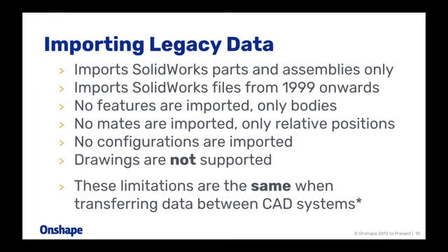a little bit more controlled and a little bit more the sort of thing you want to do if you're just making some slight modifications to a model. And again, what FeatureWorks does, it doesn't maintain any of the design intent. So, for example, if you specify this hole should be so far from this edge, it doesn't have any of that data. It'll just create the hole size, and then you'd have to manually go and add that in later. So again, there's a lot of rework in order to get a usable model.